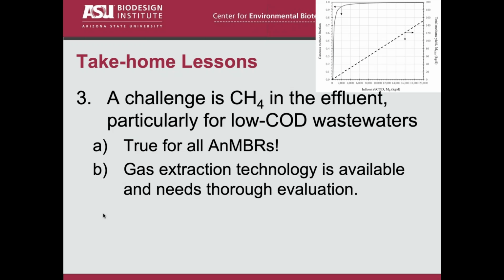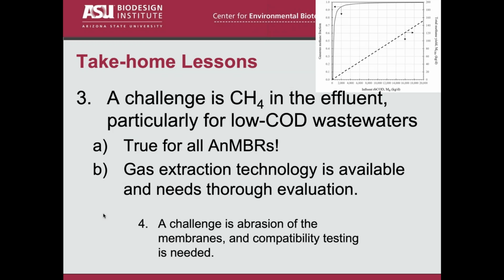And so we have challenges. Number one challenge is methane in the effluent. And this is everybody's challenge, not just the anaerobic biofilm MBRs, it's everybody's anaerobic MBRs, because we cannot be letting this methane go. We can't afford it economically, and we can't afford it from the point of view of global climate change. So we have to use it, but fortunately there is gas extraction technology that needs to be more evaluated, but at least it's out there.